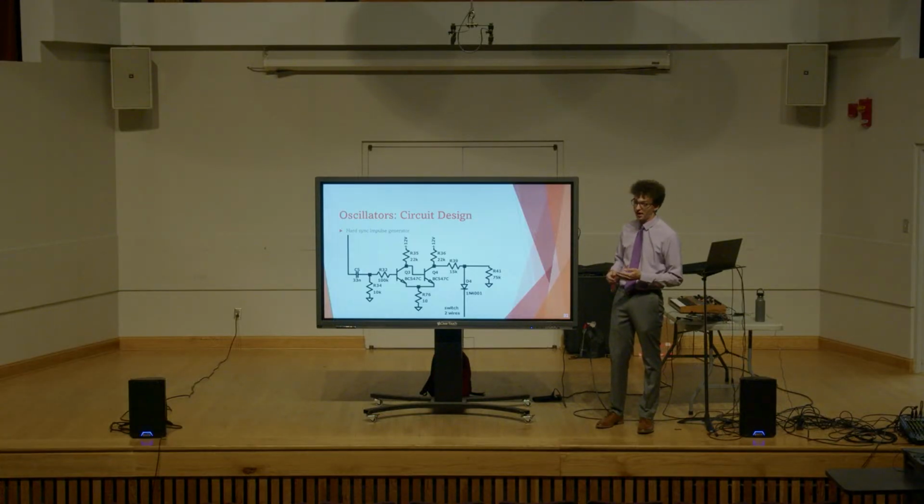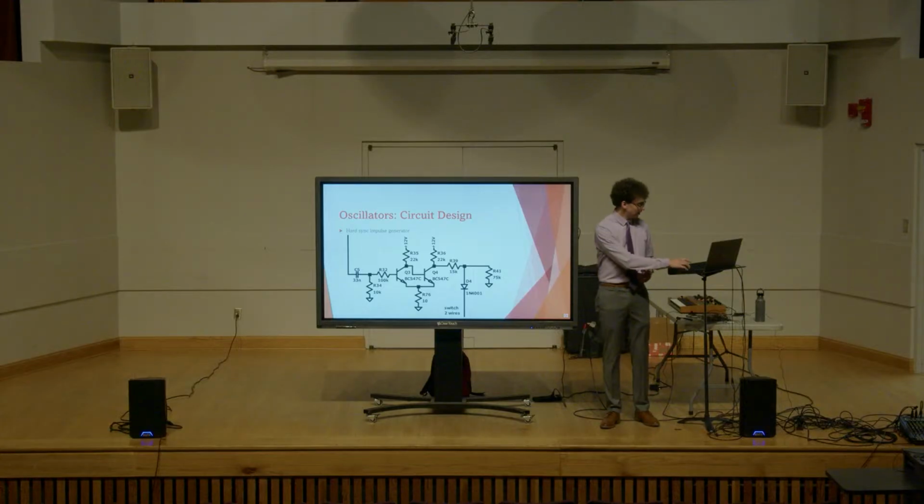An interesting issue that I ran into with this design is that when the frequencies of these two oscillators are extremely close to a harmonic relationship of each other, you get an interesting interaction between the reset of the Schmidt trigger inverter on the second oscillator and the first oscillator's prompt to reset the second. So you get a really not terrible sounding, but just unwanted harmonic output from that.